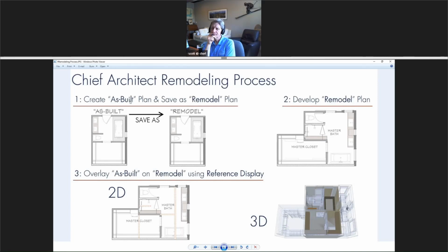That way, let's say I'm adding a hip or a gable roof, if I'm not having to cut into the roof, I'm just putting like some nailer plates, my ridge and all that, not picking up the roofing under it or the material under it. Does that make sense?